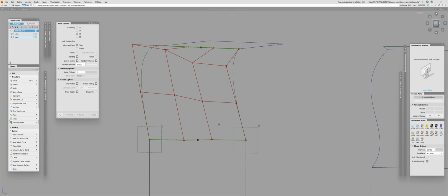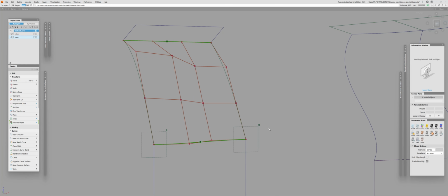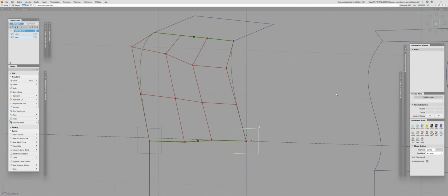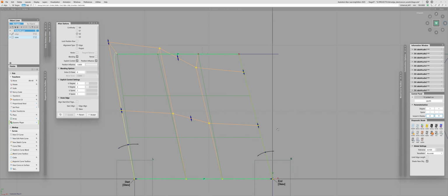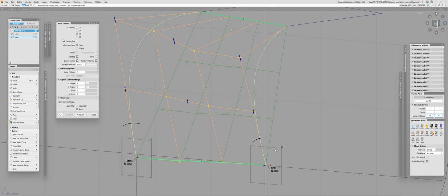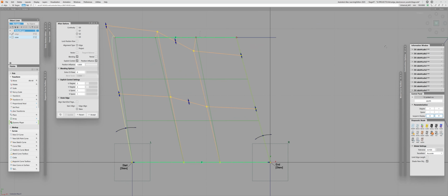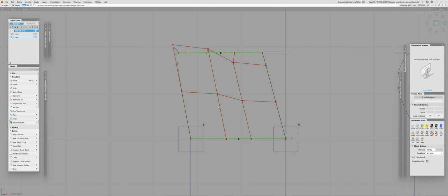If we look from the tangent plane of the surface we're aligning to, and actually let me activate this, so set construction plane, yes, this one, and look at it. Oh, look at this. Now the boundary is actually matching 1-to-1. So this is not some random angle. This angle is the same angle as from the original surface, but from the tangent plane of the surface you're aligning to at a point, so at the edge. And in fact, you're going to see that here they're not matching. Well, that's because we're looking from the wrong direction.